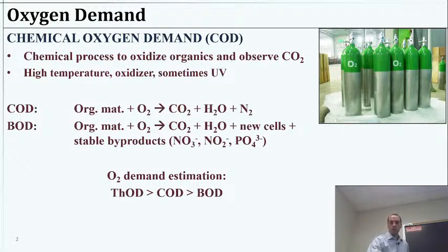All right. So BOD, then, is more accurate to what's going to happen in real life if we discharge some wastewater, but we generally do it on a 5-day type of experiment. So if we want something known about it today, then we go for COD, and that's our estimation.